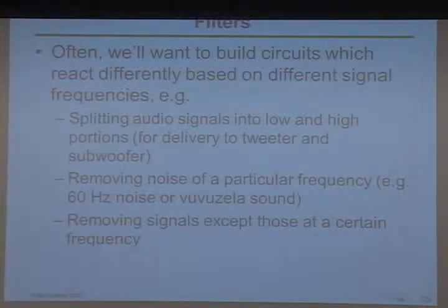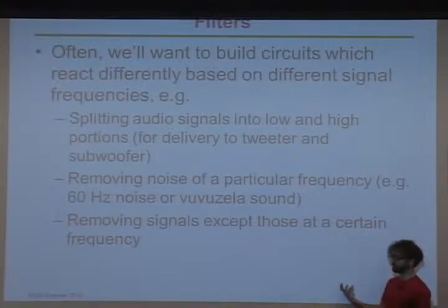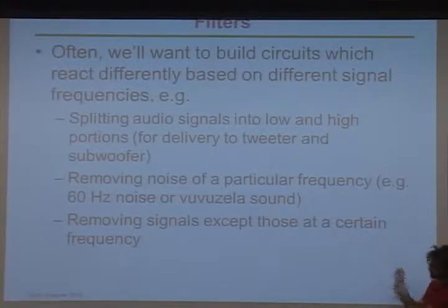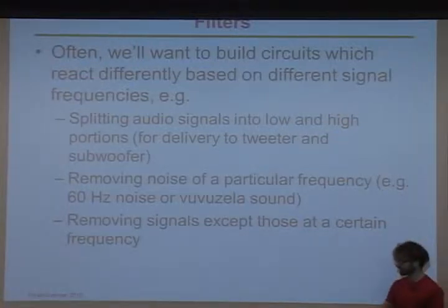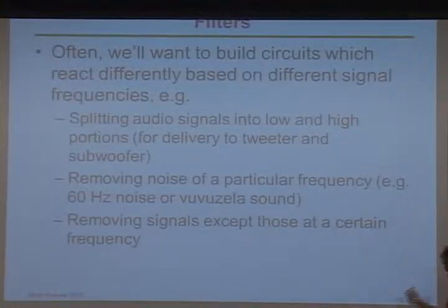So, for example, when you have a set of speakers, you take your raw, 20 kilohertz of bandwidth of sound signal. What you usually do is you separate out the low and send it to the subwoofer and send the high to the tweeters so they can do their respective jobs. You can send the whole signal to both, but it sounds nicer if you only give them what they want.